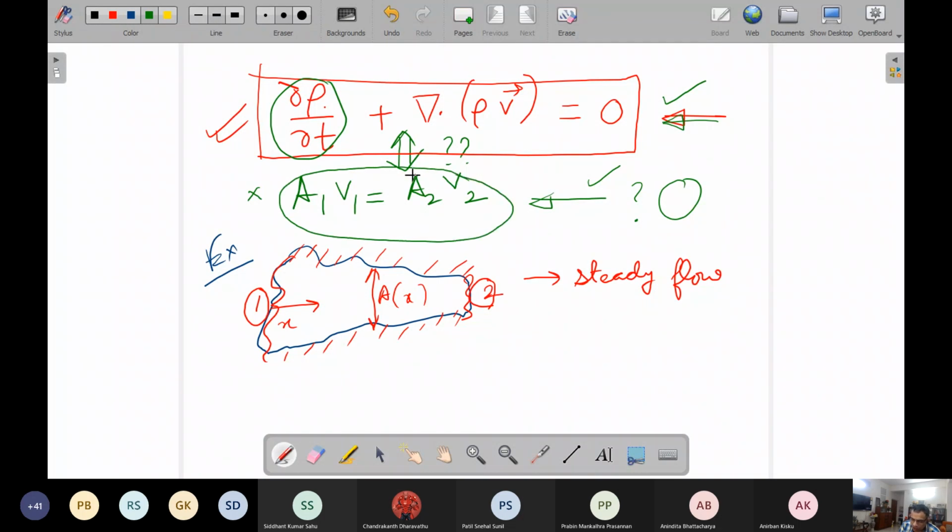This is something that books are telling us; we have not derived it. So we will neither argue that this is right nor that this is wrong, but try to see whether we can reach it. So first, if you consider steady flow, and this is very important because only then this time derivative gets to 0, we will have for that steady flow the divergence of rho v.